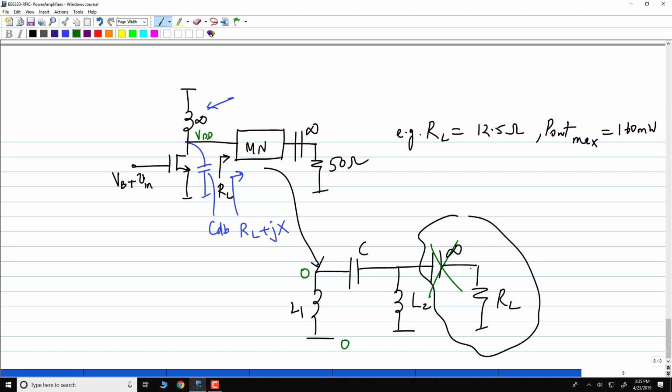There is an even simpler solution. I of course connect this to VDD. It's after all signal ground that you need at the bottom of the matching network. A VDD is a signal ground also. Now the minute you do this, note that I have both L1 and infinite inductance in parallel. Looks like I don't need this, isn't it? That's what Lakshman was saying, right? So you have an infinite inductance and the inductance of the matching network in parallel, right? What is the equivalent of L1 and infinity in parallel?